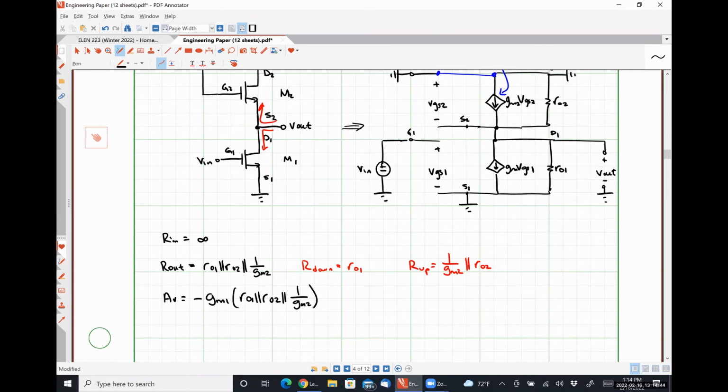Okay. So for a discrete amplifier, like one that we would build on a breadboard, chances are we're going to wind up using actual resistors. For an integrated circuit amplifier, one that we would design monolithically on a single silicon wafer, we'd actually probably use one of these representations to build our amplifier because it will take up physically less space and give us better performance.